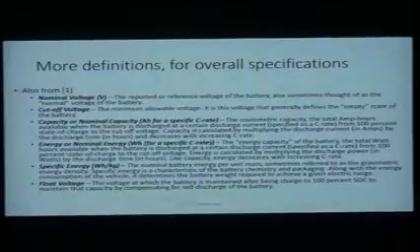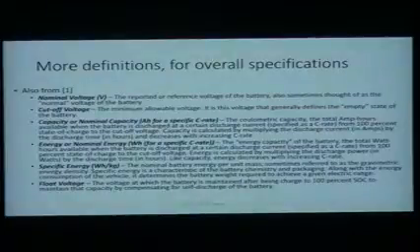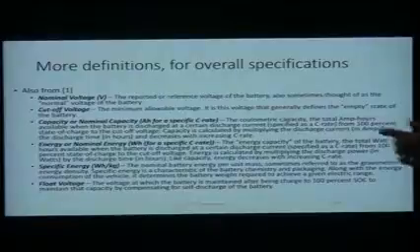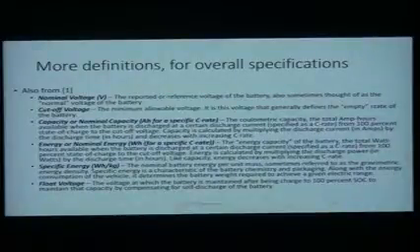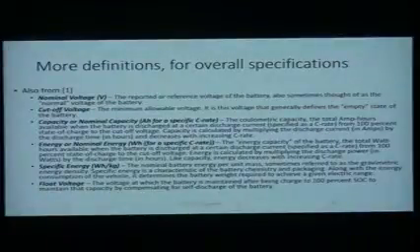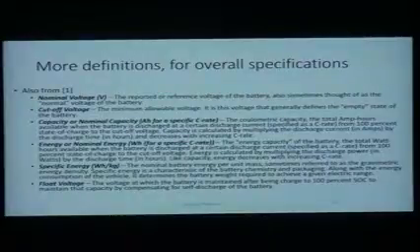So that's also important to understand. Sometimes it gets a little bit confusing because you think of the capacity in amp hours, but what you really want to know is the voltage that the device is operating at in order to get the energy, right? And so usually all these things are listed. If there is one that's left out, oftentimes it's the energy term, but you can get that by taking the capacity in amp hours and multiplying by the nominal voltage, and that'll give you a good idea of the energy.